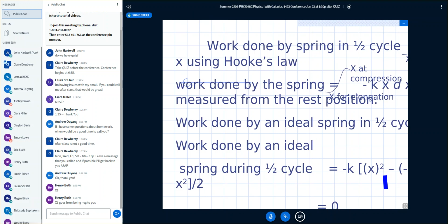If you have one force acting to the left and another acting to the right, what is the angle between those two forces? They're not in the same direction. If they were the same, yeah, 0, but here it's 180 degrees. And this is where students fail to realize that. And remember, I said we have a little sign problem here with work. We have to be a little more careful.